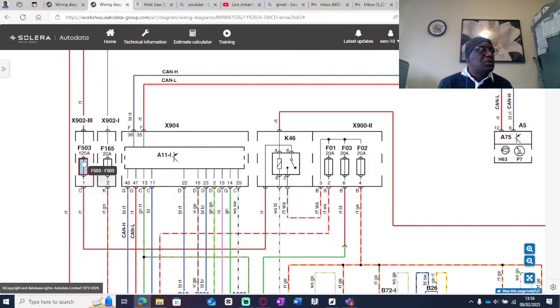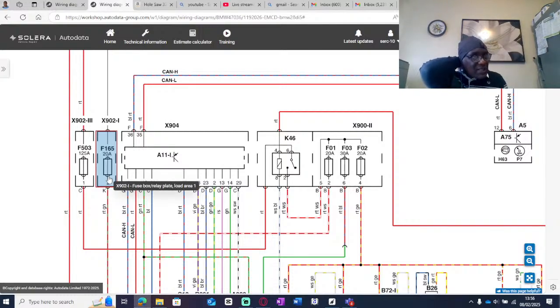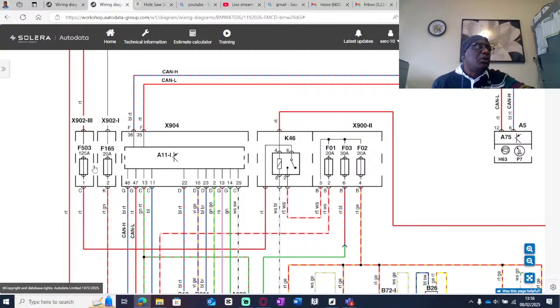What is that? So these are fuses. When you see that, that is a fuse. Okay, this is a fuse. And you can tell by this line that goes right in the center. It strikes a center line there. That shows it's a fuse. It's not a resistor. A resistor can sometimes have the same body as a fuse, but it will not have that line, which shows that we have a fuse. So, okay, fuse, another fuse, right?